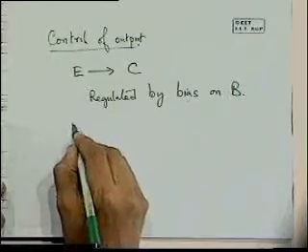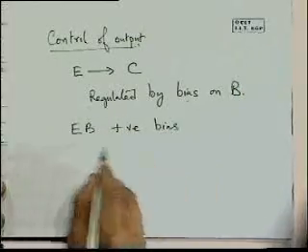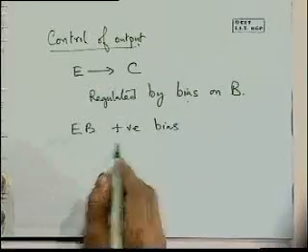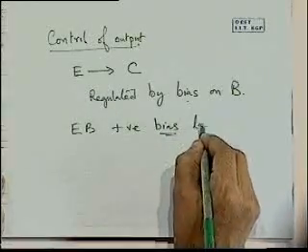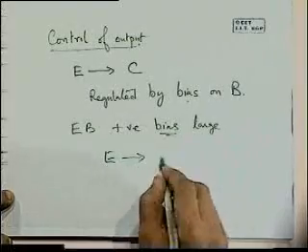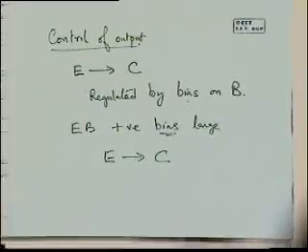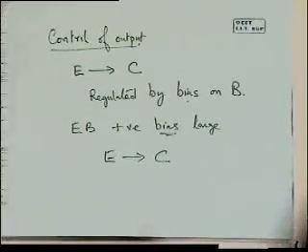For large positive bias, forward bias, in the emitter base circuit, when that is large, then we get larger current flow from the emitter to the collector, and vice versa. When you decrease that forward biasing, then you get smaller current flow. And this is the basis for using such devices in, say, amplifying the voice.